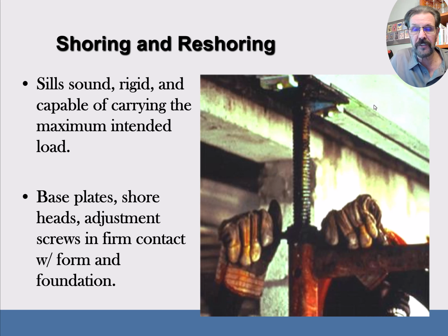Once they bonded to each other, they worked like rebar and concrete together to make a nice stiff section. And so then you can finally, once the concrete's gotten strong, you can pull these posts out. In the Hard Rock Hotel collapse in New Orleans, they started pulling these reshoring posts out too early, and that's really what caused this building to collapse.